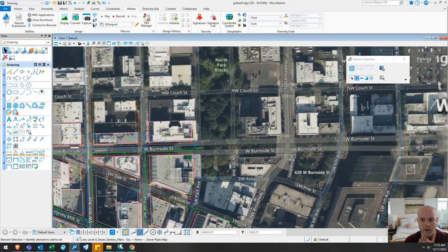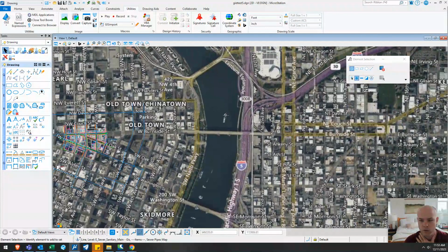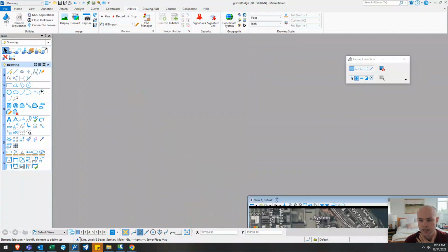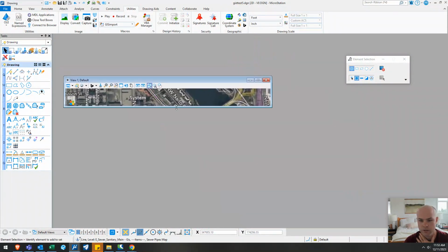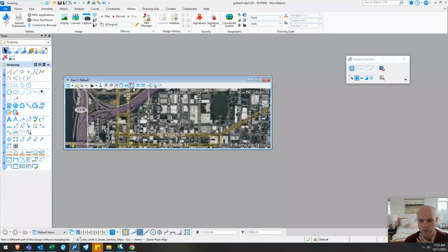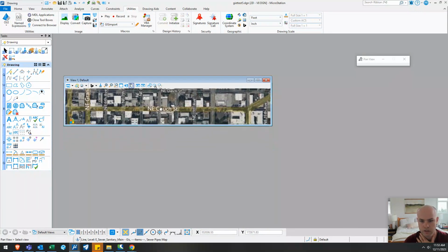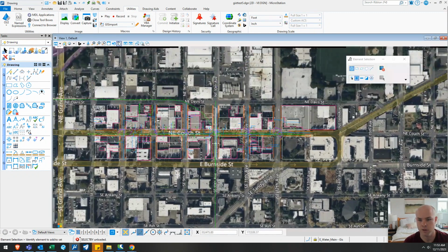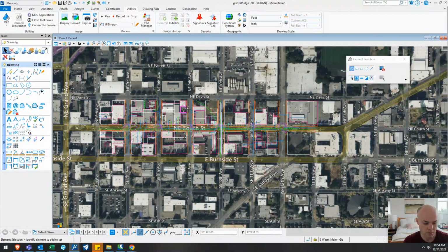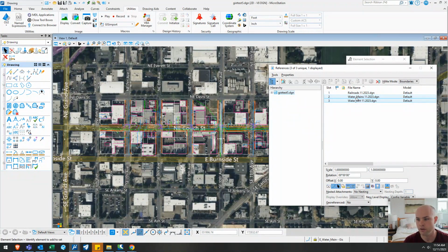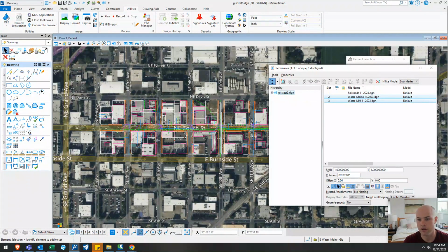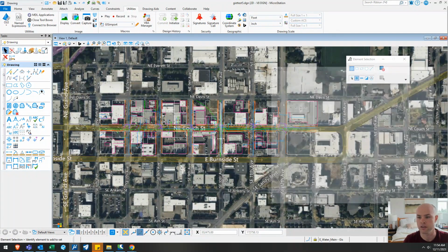One question that I got was, what if I wanted to make like a road corridor that's really skinny? Now what you do is you just take your view and you can edit it and make it however you want to run it. So if I want to have a super skinny one, say I want to do Cooch Street, just make this really skinny, and I'm going to run it like that. And there you go. And again, it just brings it over your viewport. Remember, I'd also have to bring in the railroads, water mains, and water manholes in this area. The water mains are brought in if they're less than 12 inches. Anything 12 inches or above needs to be brought in manually.